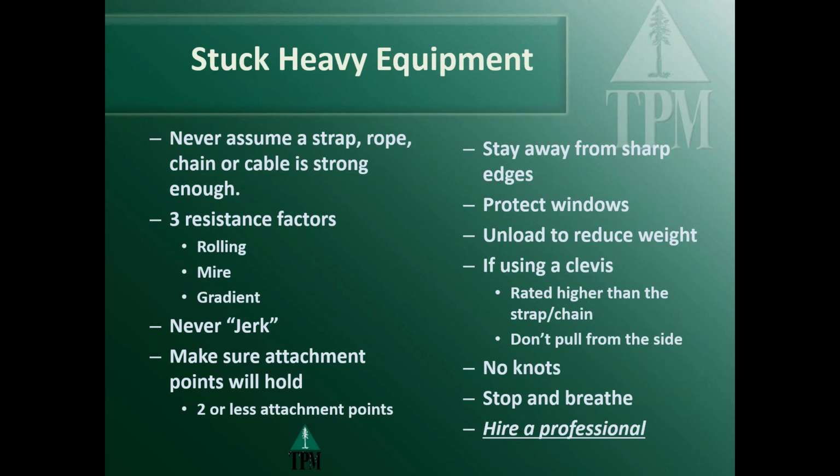So you've got just the rolling resistance of the equipment itself, but then whatever it's stuck in, so the mud or the gravel or whatever it is, and then there's also going to be a gradient one way or the other that we need to take into account. We don't want to jerk the thing out because you're going to increase the chances you're going to bust that strap or that chain.